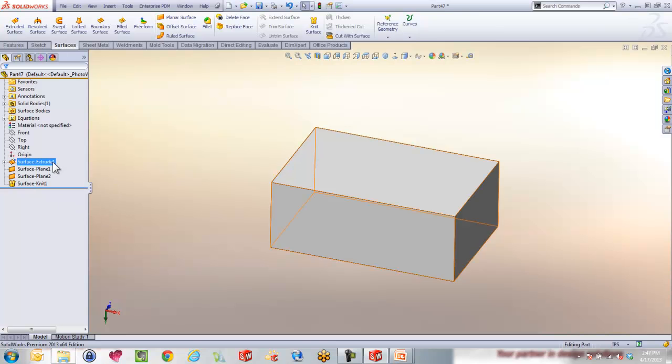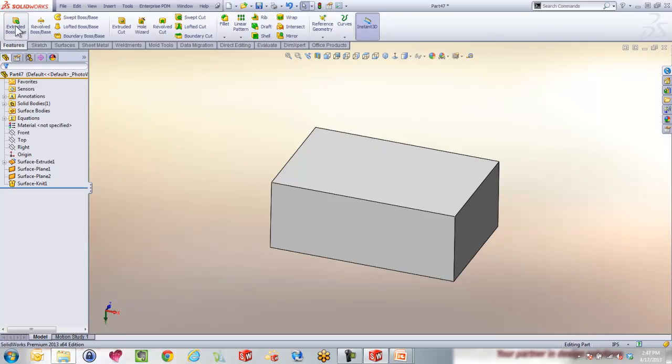But what is interesting is you see all these commands here. That's actually what happens with this feature. When you hit this feature, this is what SolidWorks does in the background. SolidWorks says, all right, let me just take that sketch and extrude it up. Let me close the lids and see if I can make it watertight.